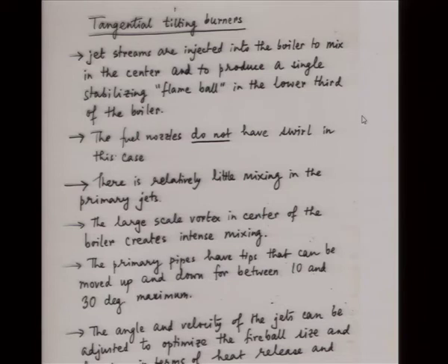The secondary air doesn't have a swirl. So in the two kinds of burners we talked about, the one which is a flare burner has a swirl in the secondary air. It's not corner fired necessarily, but the tangential tilting burners are the most popular ones where you fire from corners and fire at tangents to that imaginary circle. So that's the most popular one. This is the one which we are talking about now in this particular slide that you see.